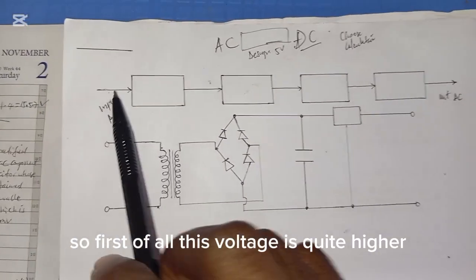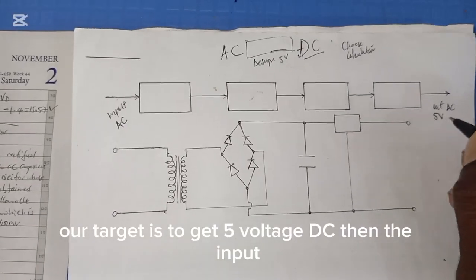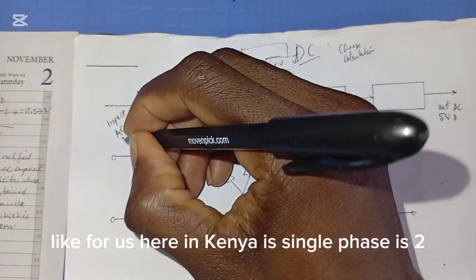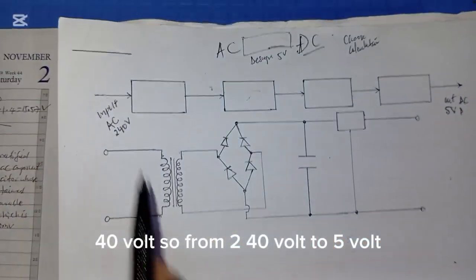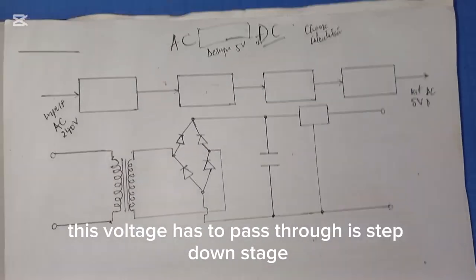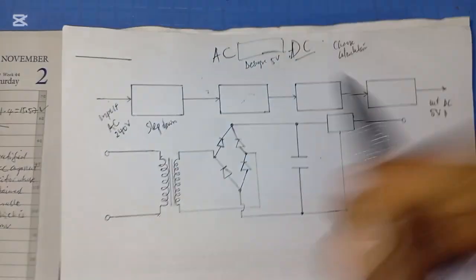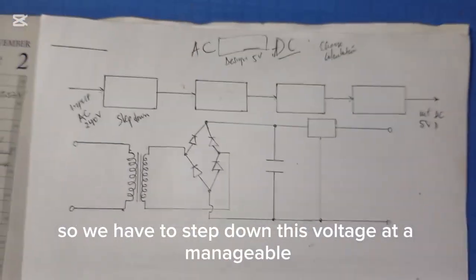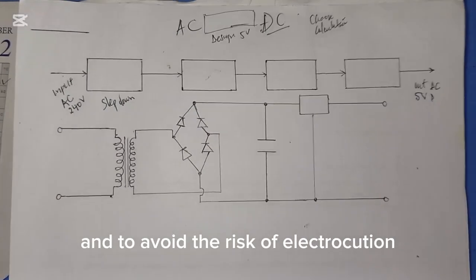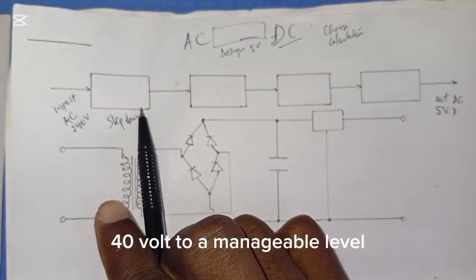First of all, this voltage is quite high. Our target is to get 5 volts DC. The input, like for us here in Kenya, is single phase 240 volts. So from 240 volts to 5 volts, this input is much higher. The first stage this voltage has to pass through is the step down stage. We have to step down this voltage to a manageable level, whereby we can manage it and avoid the risk of electrocution. So we are going to step down this 240 volts to a manageable level.